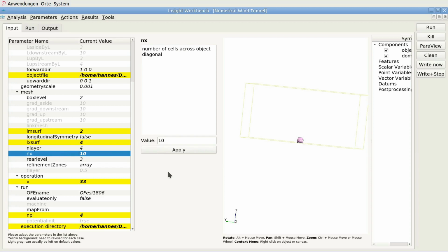Finding the right meshing parameters is an iterative process. You first start with a grid and look where further refinements are needed. The defaults are set to produce a relatively coarse grid. First I leave the default parameters. Now all parameters are set.